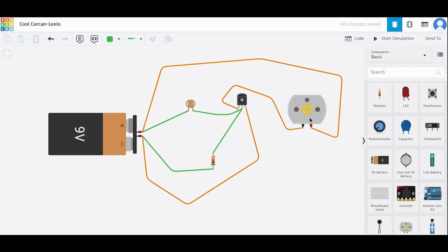So this motor, while it's turning on and off, can at least temporarily behave like a power source. And typically, you don't want any power sources to affect the transistor or any part of your circuit. So you make sure that while turning on and off, while changing the motor speed and all that, it doesn't affect the rest of the circuit.